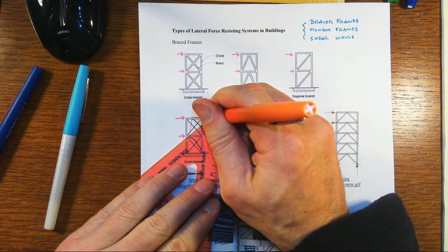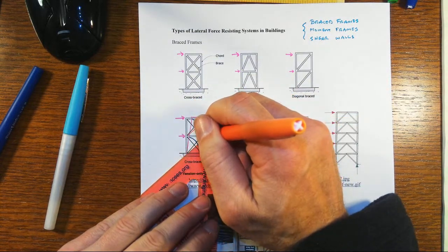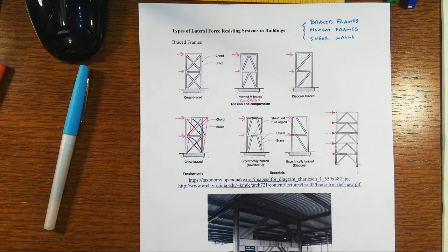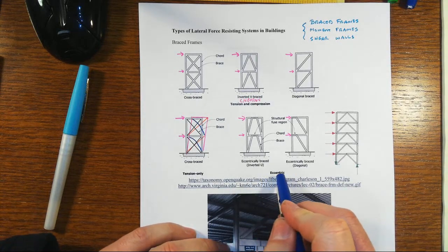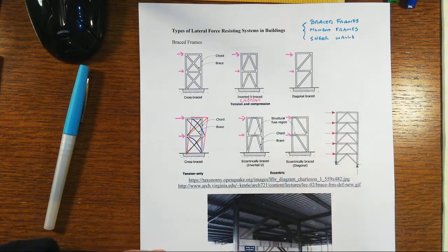And so you see these a lot in water towers still today. You see them in really old style truss type bridges, but mostly you don't see them in buildings too much anymore. Usually it's not quite as efficient, and there's a potential jerking motion, especially in a seismic type of environment. It's not really robust enough. And by the way, each of these four would be called concentrically braced frames.